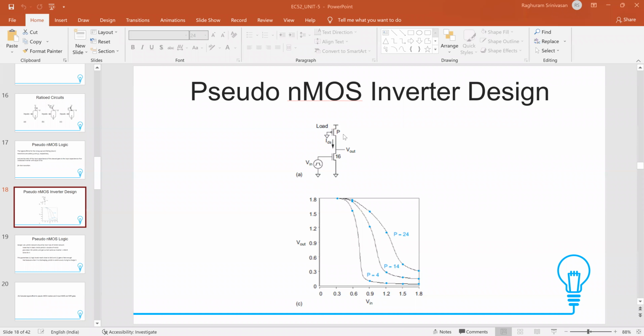And unfortunately, that's not the end of the problem. We have one more condition also. The second problem, again because the PMOS is permanently on, is that when the output is trying to go from 1 to 0, that is, this particular node Vout is being discharged... Normally, when Vout is being discharged, the PMOS network will not be conducting. But in this case, the PMOS network is always conducting. So even though... let's switch to the whiteboard.